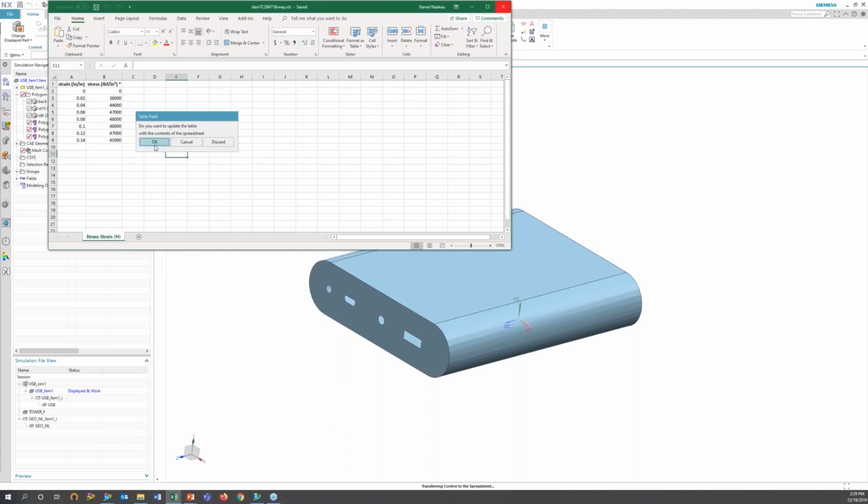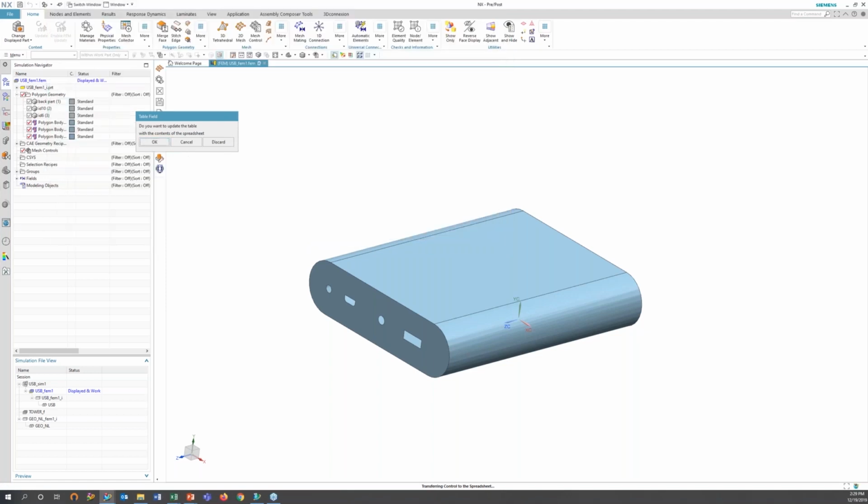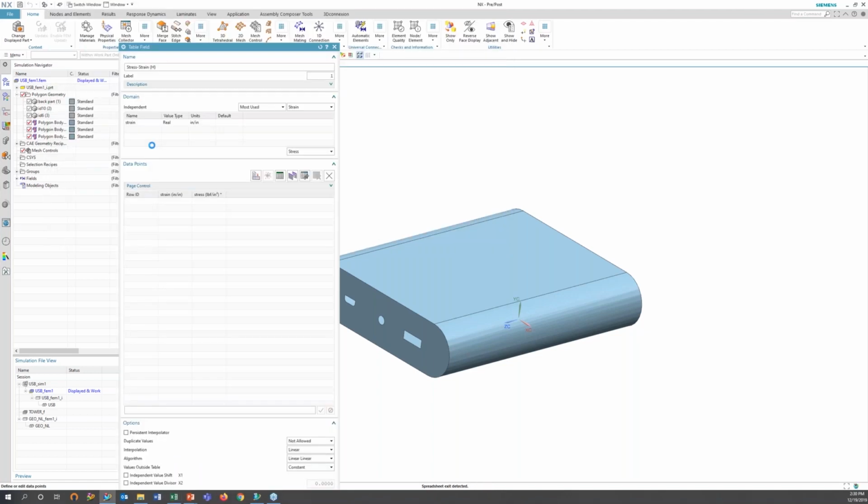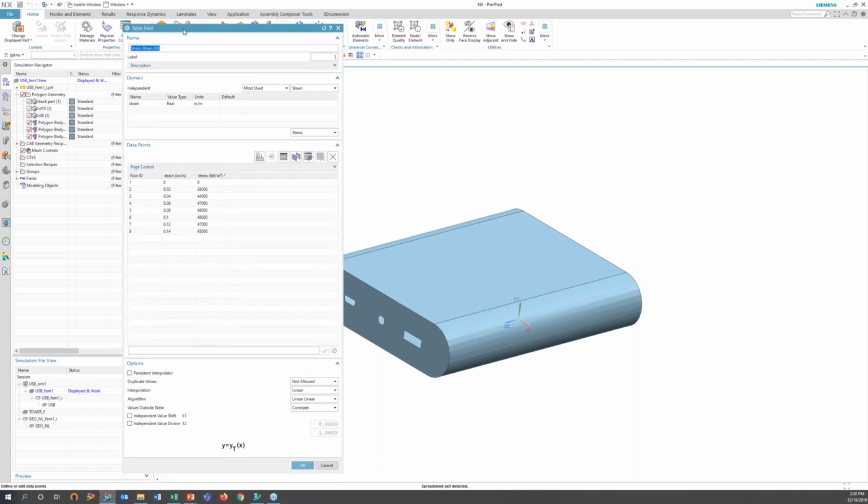So a good example would be if you are having issues with your model converging and it wouldn't work, you can toggle it off to not include the large displacement, and it should help it converge because it doesn't have to deal with the geometric nonlinearity. But most of the time, the reason why you are in here is because you want to toggle that on. But maybe you just want to make sure that your material nonlinear model that we're working on right now works. You can toggle that one off and use it for troubleshooting.